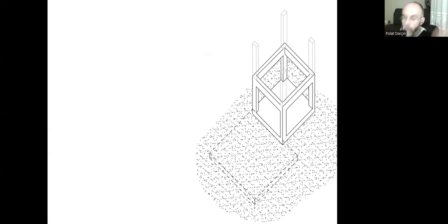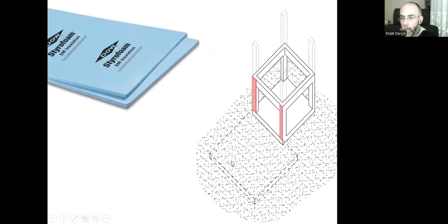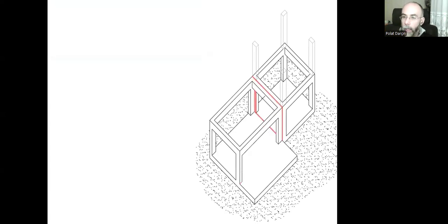Once they are set, once the molds are removed, in order to create the new building, the neighbor building, these columns, we can use XPS boards. First, we can cover the surfaces of these columns and beams with 5 centimeter thick XPS boards. And then we do the molds for these columns. And those boards will work as the molds, and they will create that 5 centimeter gap, and they will fill the gap. So we don't need to remove them. We can leave them as they are.